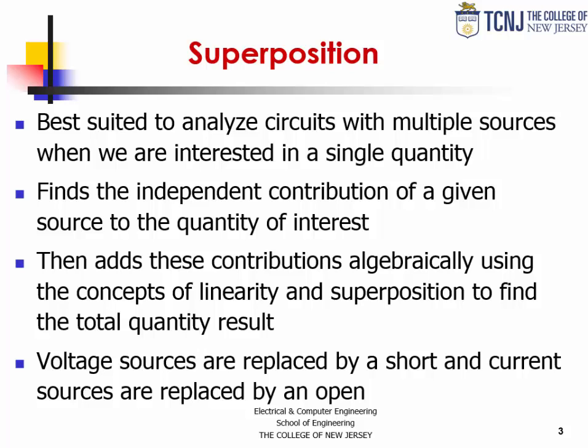So superposition is a technique that is best suited to analyze circuits that have multiple sources, so a combination of multiple voltage sources and current sources. But we are interested in finding a single quantity in the circuit.